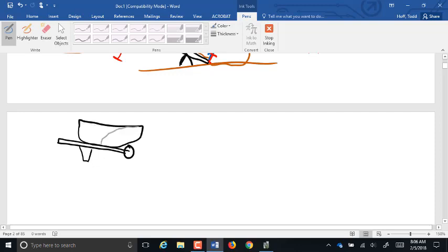You load it heavily up front. The reason for that is the center of that load is closer to the pivot point. So when you lift here, this is moving up less distance. The further that load is up here, the further that load has been lifted up when you lift it. When it's above the wheel, it barely moves up. It takes very little force.